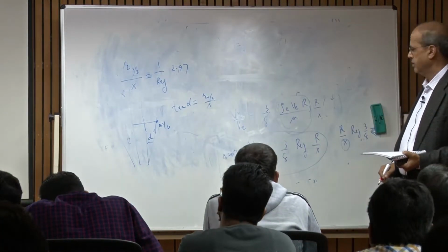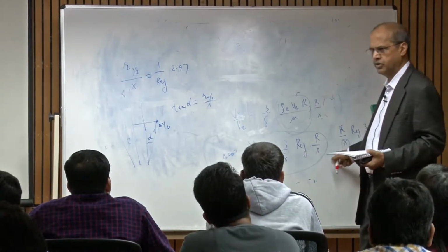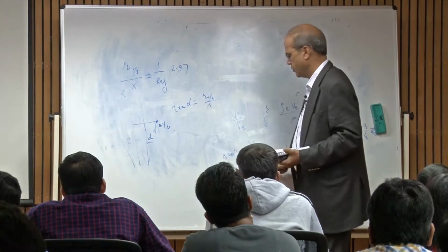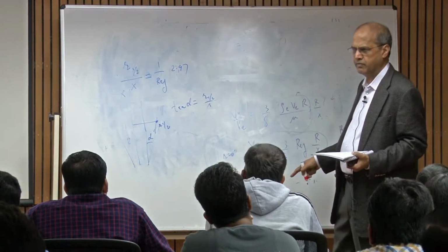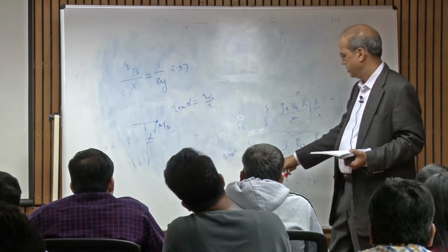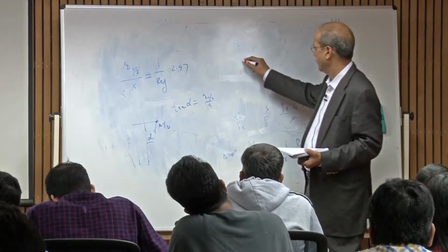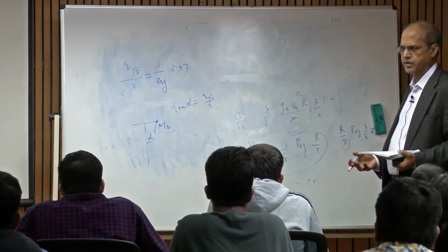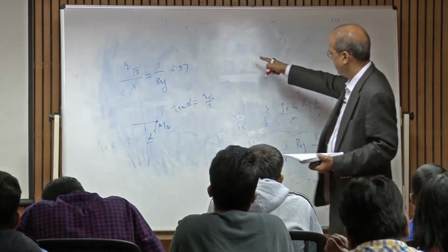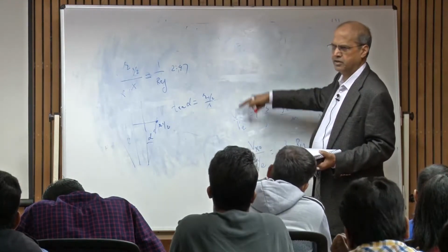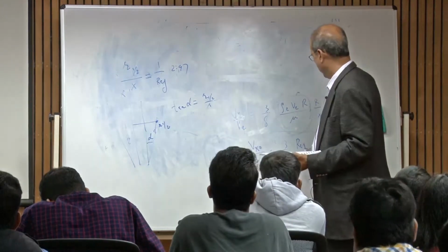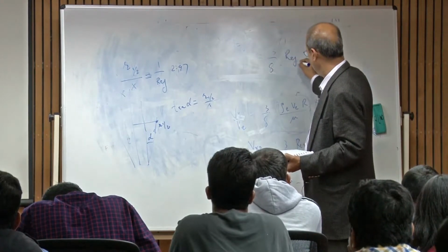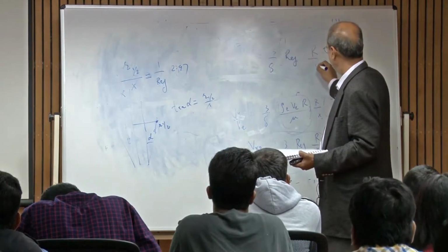YF at the center line has the same solution, divided by YF, which is 1 at the jet boundary. This is the velocity, so this is 1, because at the jet boundary YF value is 1. So, this gives the value along the center line of the jet. So, that will be 3 over 8 REJ r over x.